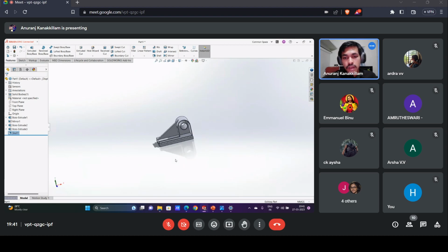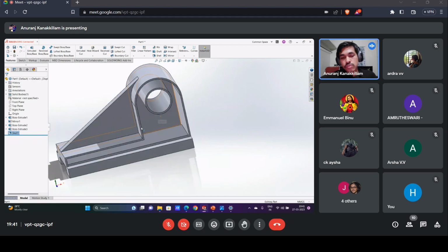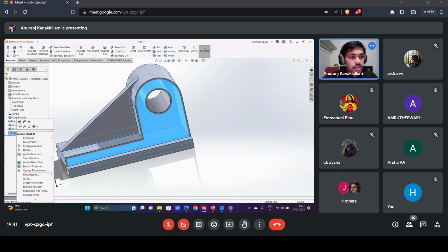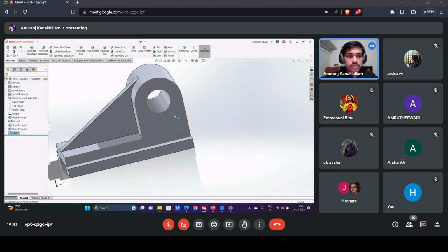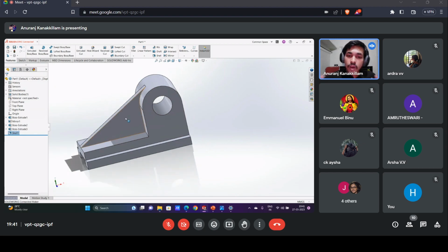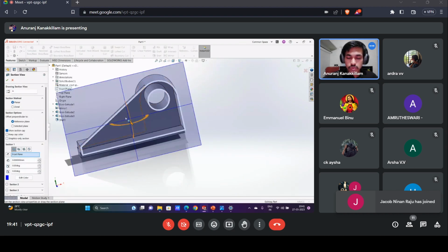And so now I need it similar to a football. We can't see it's hollow, but it should be hollow. For that, we remove this face. Just give shell. Now it's hollow from inside. But how can we know? That's why I showed you this section feature. So when we cut it, we can see. Similarly, when we cut the football, we can see it's hollow from inside.